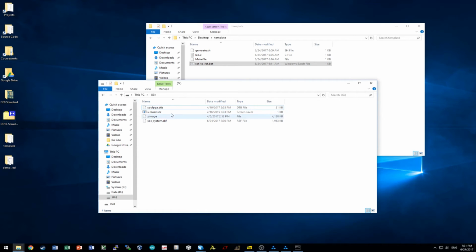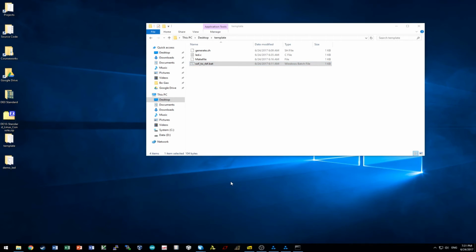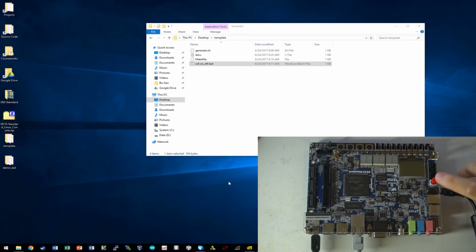Alright. This is one way we can load our bit stream to the FPGA, that's on U-boot, or as we demonstrated last time, we can use the configfs, or you can simply plug in a cable into the Byte Blaster and just load the FPGA from a Quartus programmer. And that's pretty much the three major ways to do this. I will just use U-boot to help me doing this. And let's boot up the FPGA. Let's see what will happen. Alright, let's boot up the system.